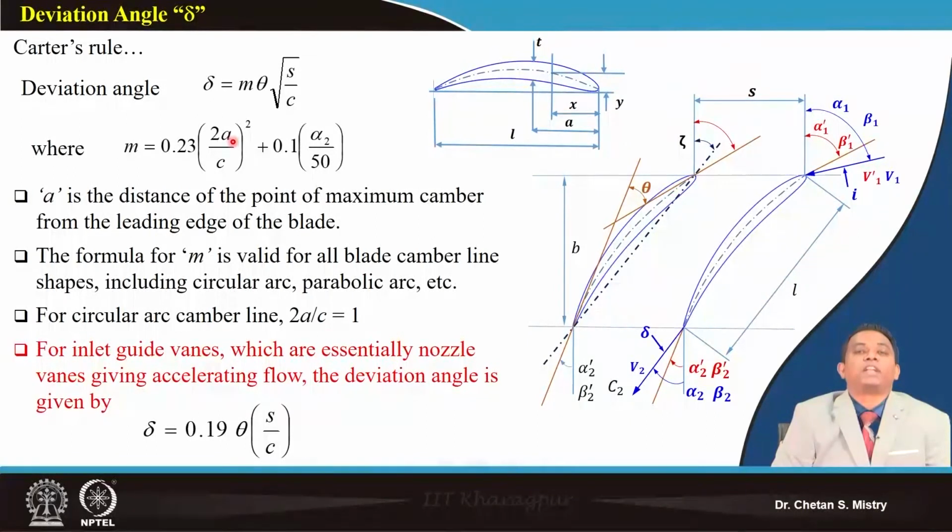Now, with the availability of computational tools, people realize what is happening near the trailing edge. Based on flow visualization, Cp distribution and detailed flow field study, people modify this deviation angle to make the flow line up with what we expect. So computational tools are helping us decide the deviation angle.